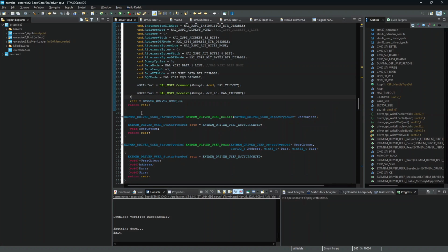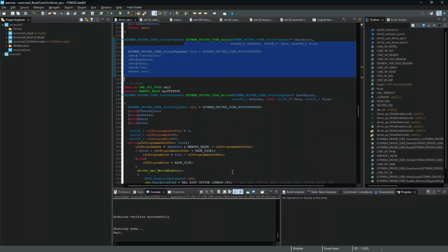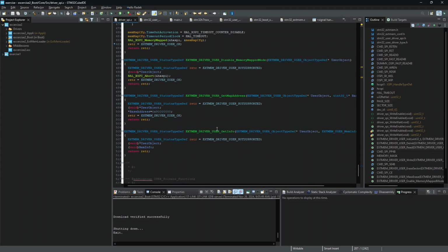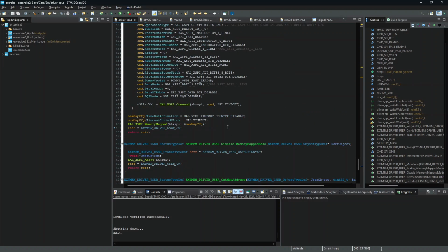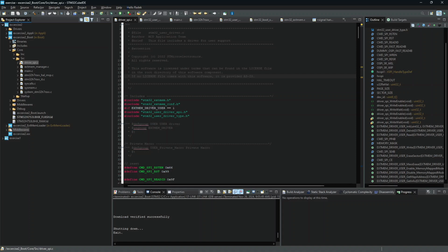And we can move into the external loader because all this is now implemented how the loader wants it. We don't want to use the init because we will use the execution in place. So this has no meaning. The read will also not be used because we have the reading as memory mapped. And everything is used except the get info, which is also not used in this case. So we can simply take this file, the file which we have here, and copy it inside the external loader.